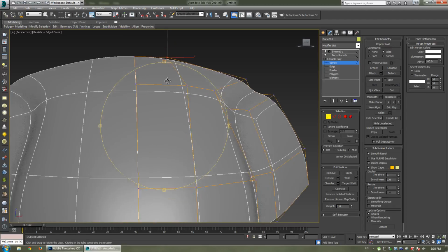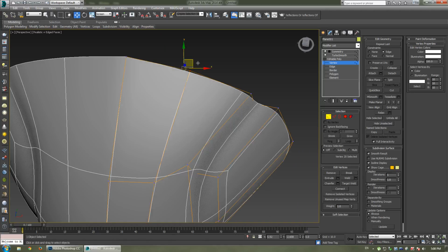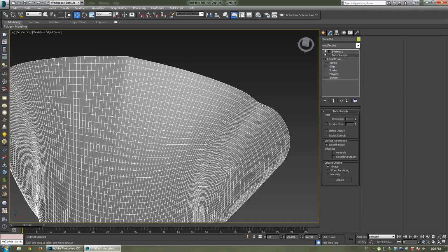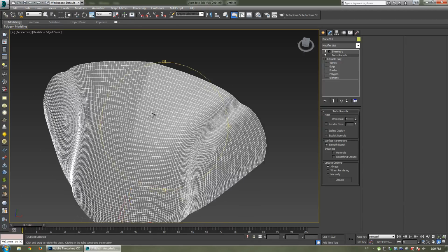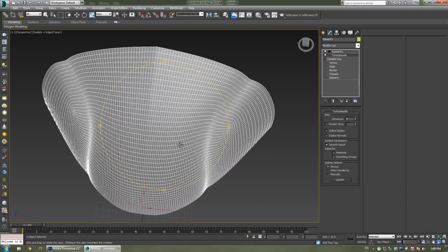So to do that, I'm going to go to the correct camera angle. Once again, I'm going to use Alt and right click to swap to screen. And then I'm just going to move it so that it's roughly in the middle here. What that will do is create a much more even distribution of polygons. And you can see there you go, it's much more even. You're making it so much easier for 3ds Max to produce a clean result doing this. Every single vertice on your mesh, you need to be aware of that and look for those problems.